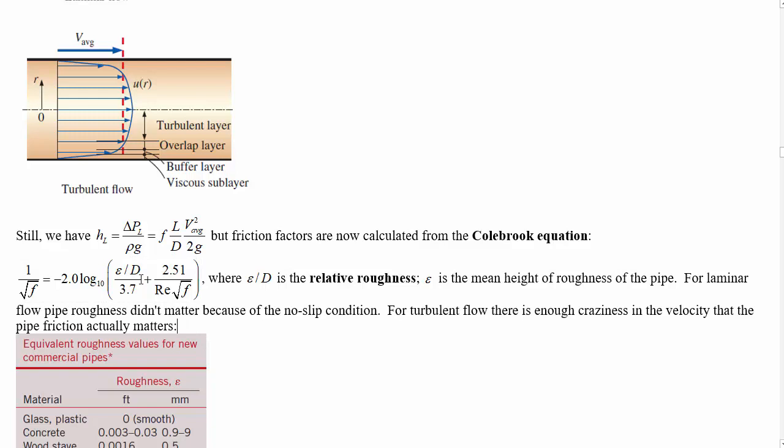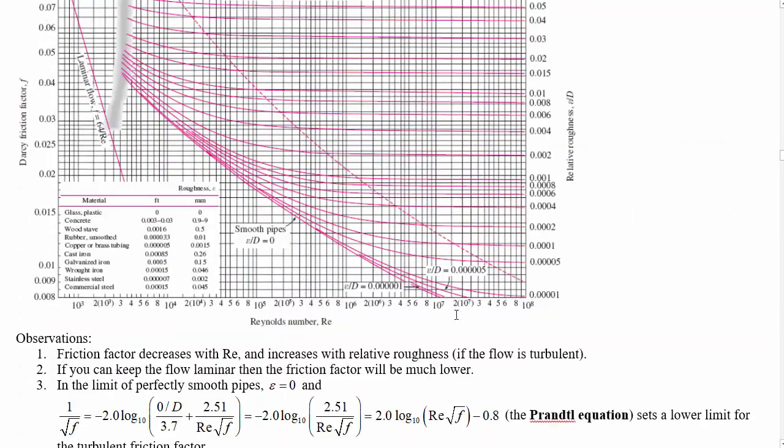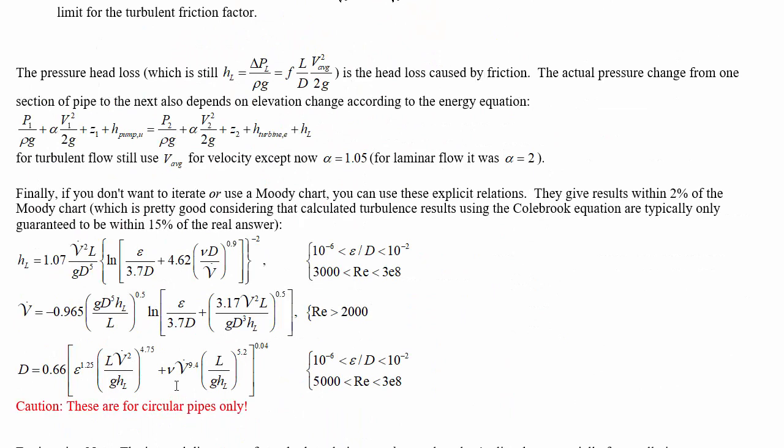Well, the diameter doesn't just show up right there. The head loss doesn't let you determine what the friction factor is unless you know the Reynolds number, and you can't find out the Reynolds number unless you know the diameter and the velocity. The flow rate doesn't determine the velocity if you don't know the diameter. So diameter is really coupled in this equation in a lot of different ways, and having a shortcut to solve for that directly if you know the flow rate and the head loss that you're looking for in a given length of pipe is definitely a real time saver.